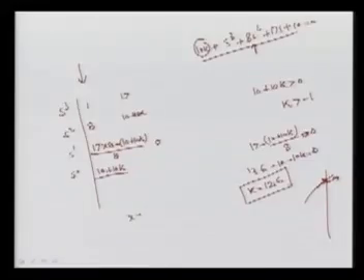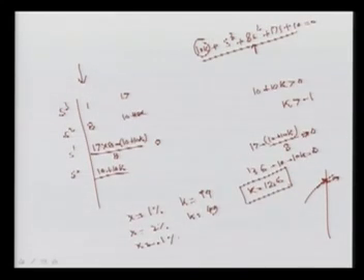So for accuracy 1%, we saw k required is 99. For 2%, we required 49 gain, and for 0.1%, k was 999. Means if you are going for more accuracy, gain is more, but here it may change and it may cross this. For this k we can determine what will be the accuracy as well, no doubt we can represent.